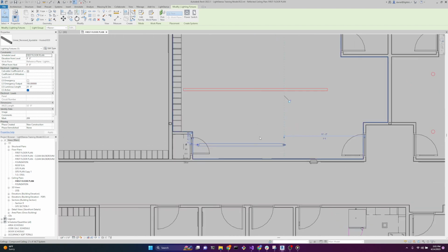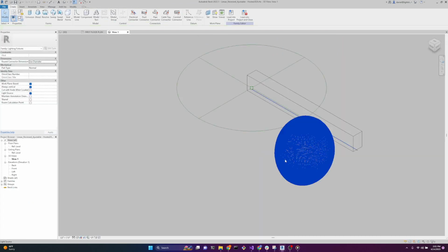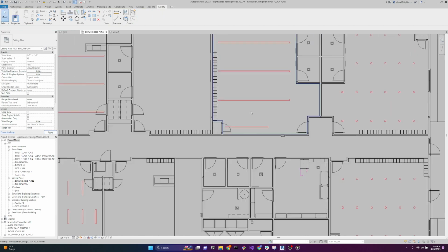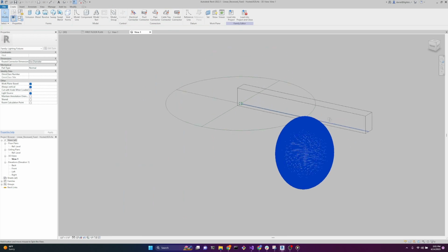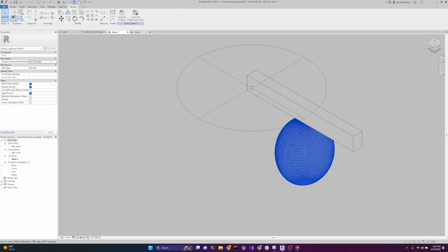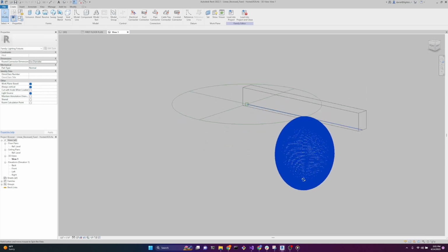And so I'm going to go and select this light fixture, right-click, edit family. And so I want this IES light source, the center of it, to change its position, whether it's an instance linear or whether it's a fixed type linear. And so if I went over here, and went to this guy, edit family, we can also see that this is centered on the light fixture itself. So in order to get them centered on the light fixture itself, we'll start with the fixed length linear.